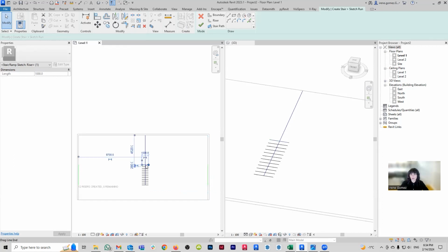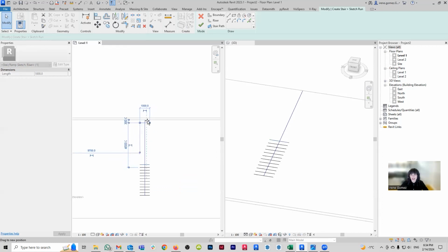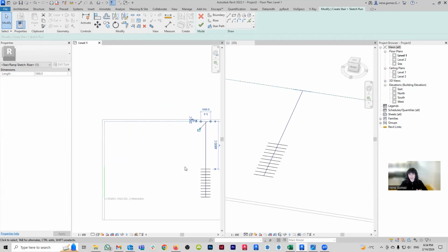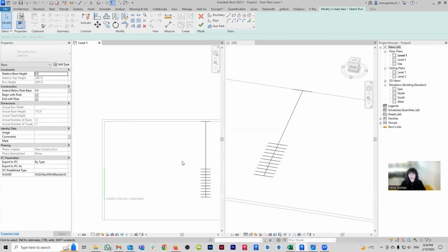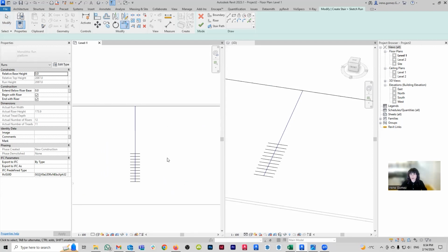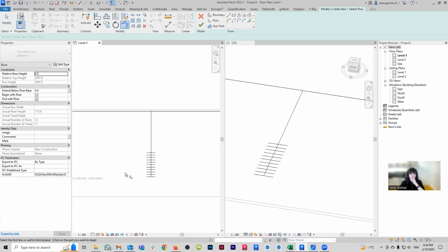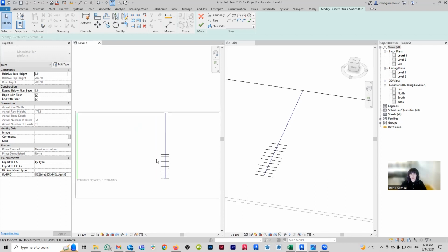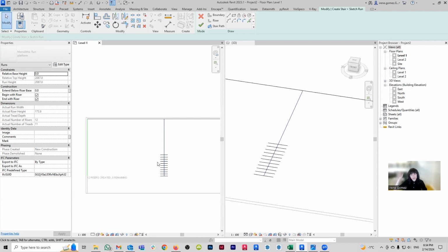But the easiest way to do that, we're going to take our last step, and that one is going to be against the wall. So I'm just going to leave it straight because that one should follow the boundary of your wall. Now I'm going to use the trim tool, TR, trim, and I'm going to trim those two lines and then these two here. Finally, I'm going to start playing with my lines. The reason that I keep these lines is because, again, I have a hard time counting. So having these just makes it easier for me.